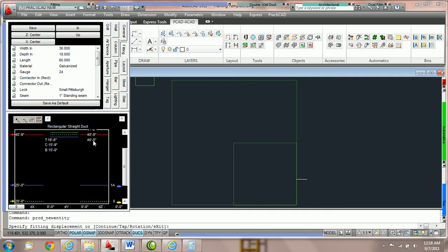foot in absolute elevation. So we can toggle between what's relative bottom, and it does not have any effect on our tags, and we're going to show that to you now. We're going to change the 20 foot back to relative bottom. So we come here, click on our yellow button, and that'll switch it to blue, or relative bottom. Once again, I like to use the elevation marks view because it centers everything and makes it easy to scroll through my elevation box.